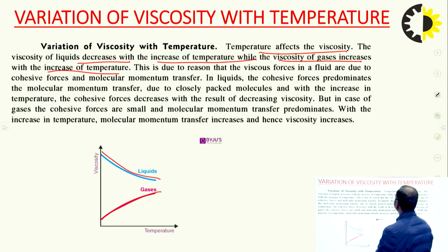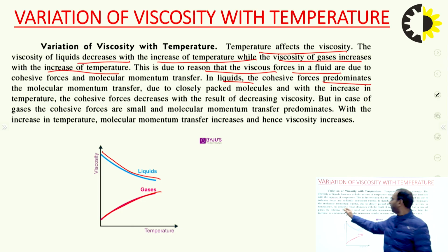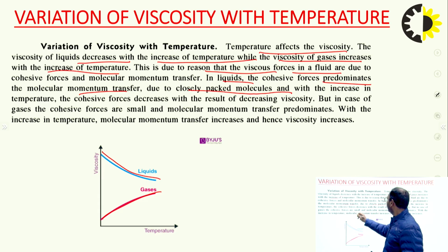This is due to the reason that the viscous forces in a fluid are due to cohesive forces and molecular momentum transfer. In liquid, the cohesive forces predominate over the molecular momentum transfer due to closely packed molecules, and with the increase in temperature, the cohesive forces decrease, with the result of decreasing viscosity.